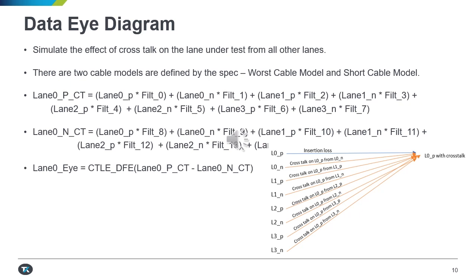At the data rate of 12 Gbps, the source eye diagram is performed at TP2 EQ using Cat3 worst cable model and using 8 dB CTLE and 25 mV DFE. For Cat3 short cable model, it is recommended 1 dB CTLE without DFE. Basically, CTLE and DFE both are applied if data rate is at 12 Gbps. For lower data rates such as 3G, 6G, 8G and 10G, source eye diagram is performed with worst case model using 8 dB CTLE and short cable model using 1 dB CTLE without DFE.